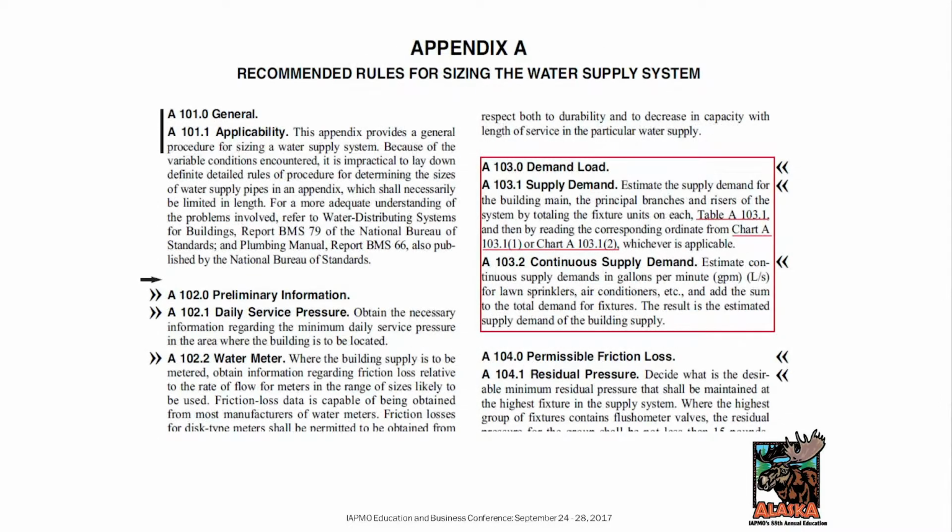So basically, what this water demand calculator is doing is being an alternative to what's boxed in here. You're no longer going to be making reference to Hunter's curve or to fixture units. You're going to estimate the demand load using the calculator. The rest of Appendix A is the same, standard procedure as you would size a plumbing system that's for years, common engineering practices. But we're just looking at substituting the calculator for this. Do we have any questions? I know there was a lot of statistics, and that could put a lot of people asleep.